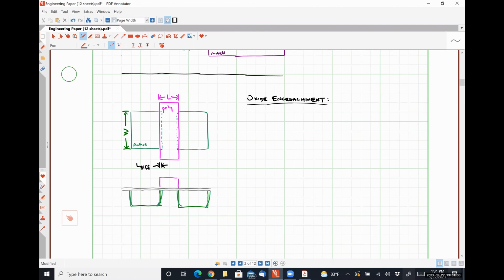So if we don't cut our hole large enough, the effective width of our transistor gets smaller. Another way to think about this is float, right? All of these patterning steps that we're doing, we don't actually have any super critical control of the dimensions that we're getting, because it's all based on chemical processes, etching processes, and we understand the statistics and probability of what we're doing, but we don't have any finite control over the actual dimensions of these things.